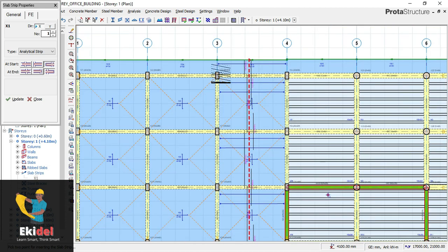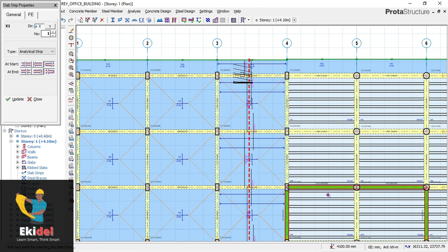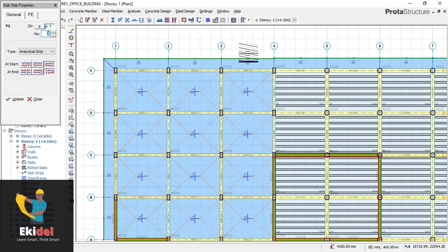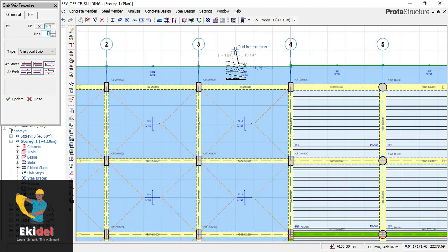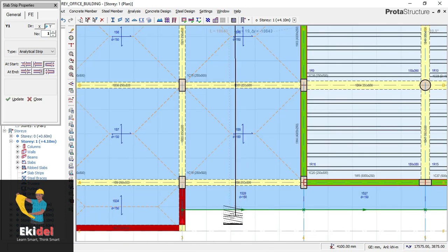Okay, so right now, I made a selection of X direction, but this is a Y direction, so I'll just right click and then delete it totally, because I have to choose Y direction if you're beginning from Y direction, and then just repeat what we have just done. So I'll click somewhere above that and then hold my control key down, or just go down first to locate my ending point, which is still a cantilever end, and then locate here, holding my control key and click.